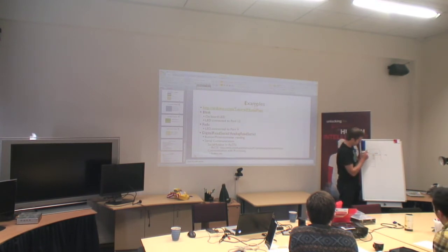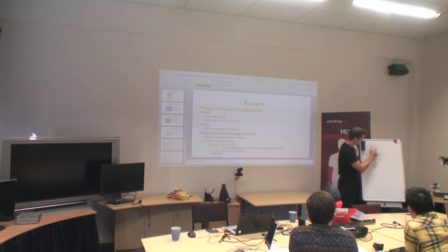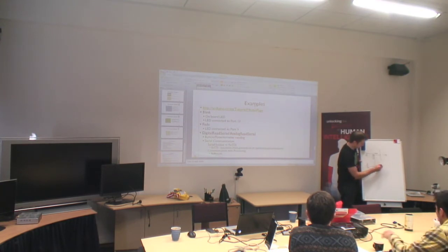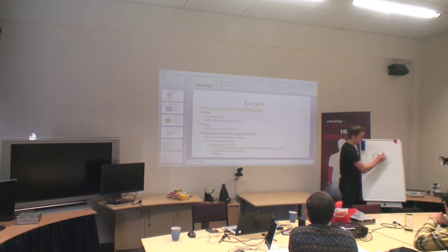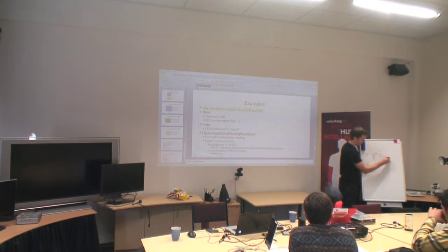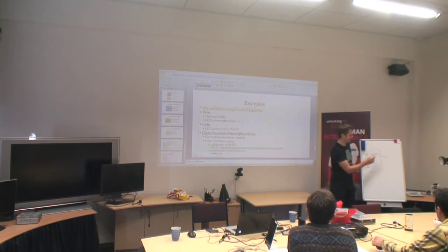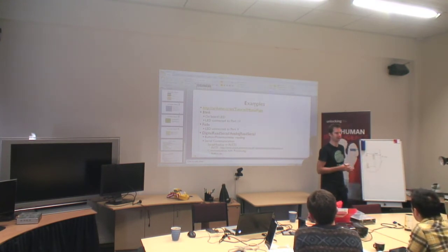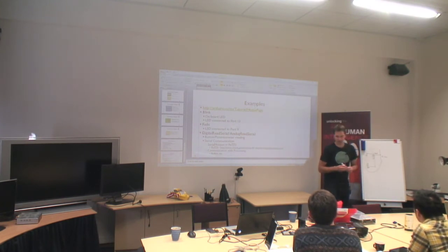If this was instead connected, say down here, we have ground or 0 volts. And if that was connected in like that, our digital read would return a value of 0, which equals 0 volts. So it's just a way of looking at what power is running through that line and saying, is this 5 volts or is this 0 volts? And it returns that.